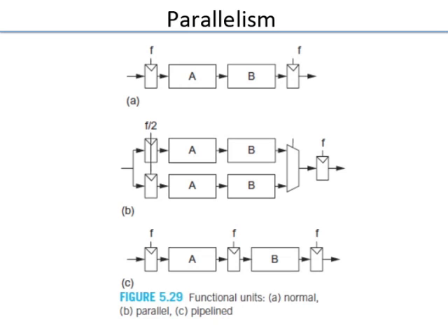You have to operate it at the most efficient voltage, the least possible voltage at which you can run the chip at that F by 2. Otherwise, there is no point in going from here to here. Frequency is low, power consumption is low, but there are 2 of them. So you cannot say that; that is not the way to look at it for this particular case.